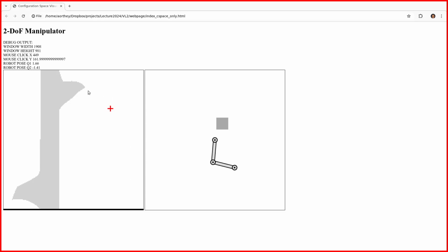And in the configuration space, you have 2 regions. One region where the robot can just move around, which is this white one. And we also have a gray region, which is basically all the configurations which are in collision with the obstacle. So if I go into the gray region, then suddenly the robot is also in collision with the obstacle here.